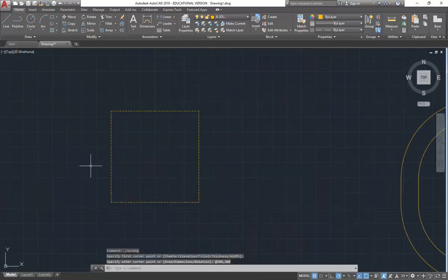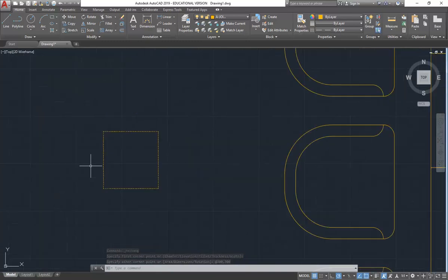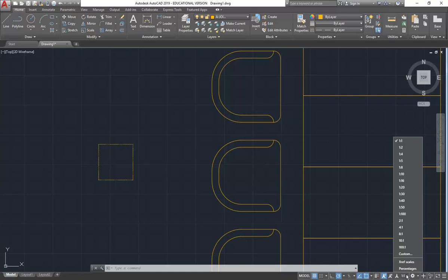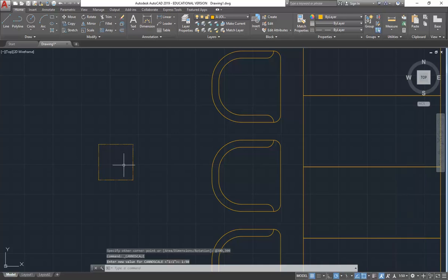And you might be thinking, God, well, those lines, they're pretty small, those dashes. I'm also going to show you a slightly different way of setting the scale to what might be in the notes or what James maybe would have shown you, because those are the old ways. This is the new way, well, the new way, it's been there for 20 years, but a lot of people still don't know it. Use the scales. That's the best way. So what scale do you reckon you'd be using for this drawing? And for a lot of your interiors projects? Exactly, 1 to 50. That's the one you should be getting used to. So if you're not sure, use that. So these lines should have changed size.